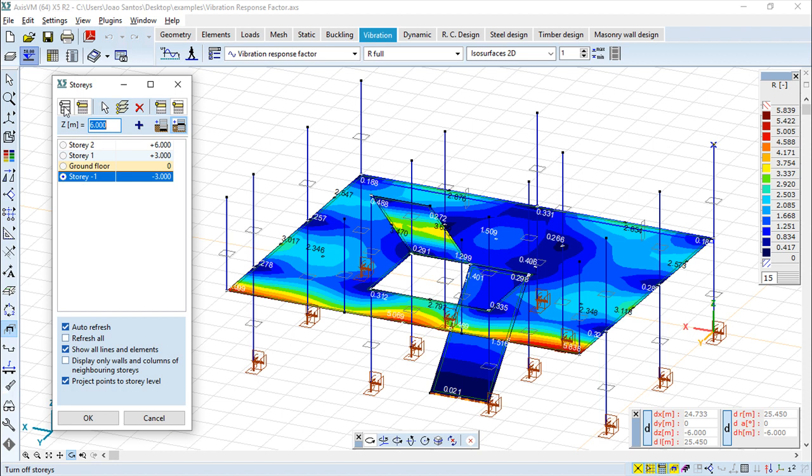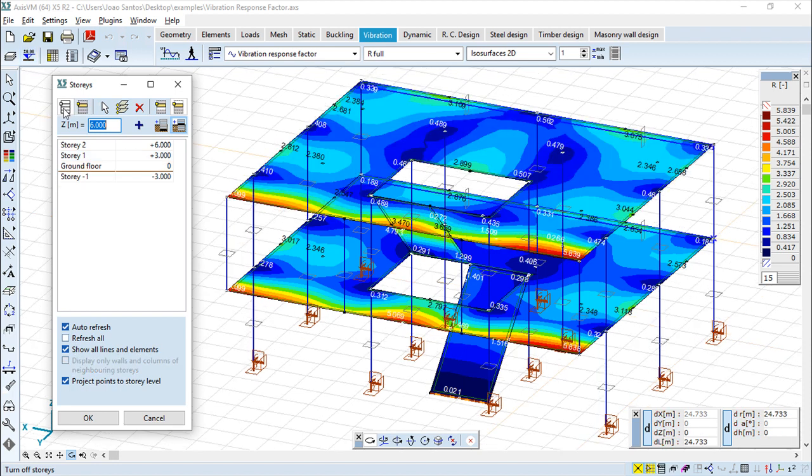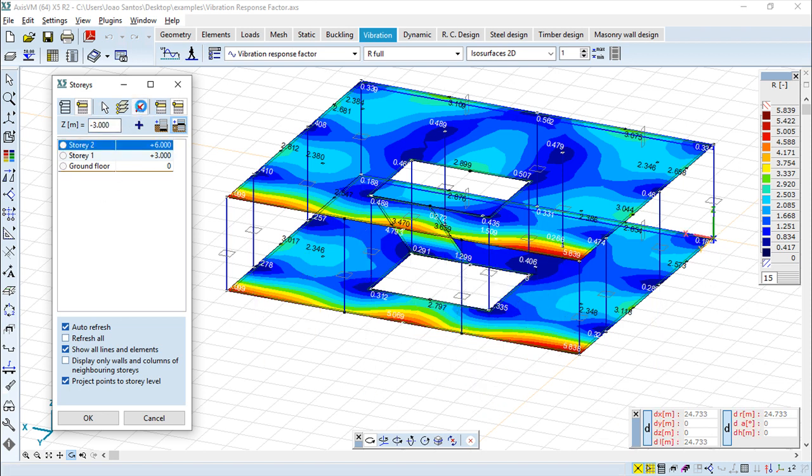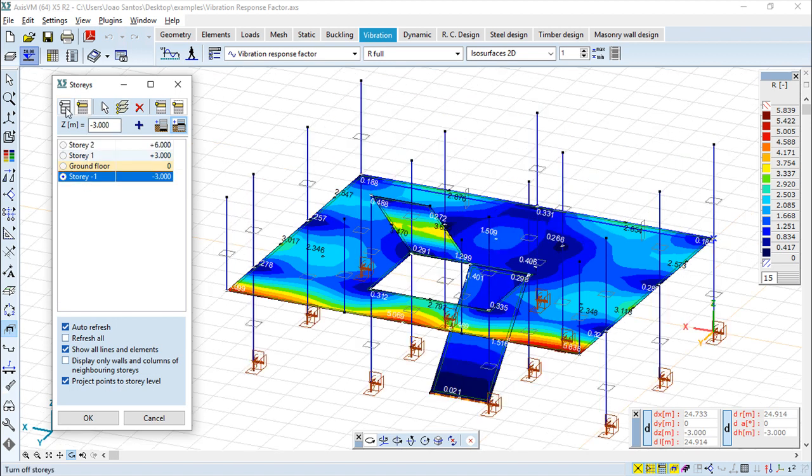I can turn off the stories, okay, and then I see all my model, and in this button, as you saw, I can choose which one is the current one. I can delete stories also, so I can delete one if I want. For example, this one I can delete. I will edit again now because I wanted to have it here. And I have also this function here, which allows me to find the story somewhere. Okay, I don't have anything to find, so no big issue.